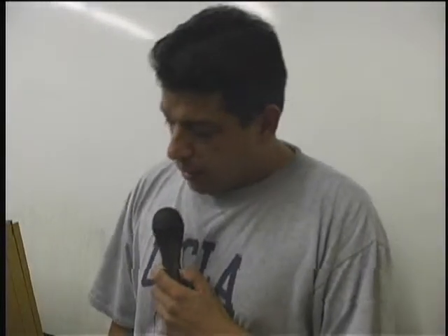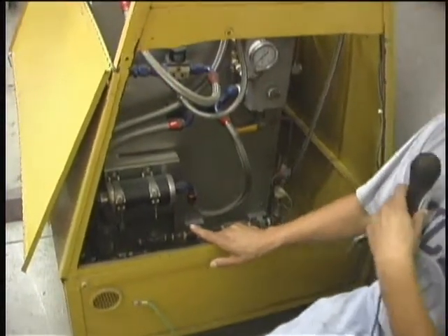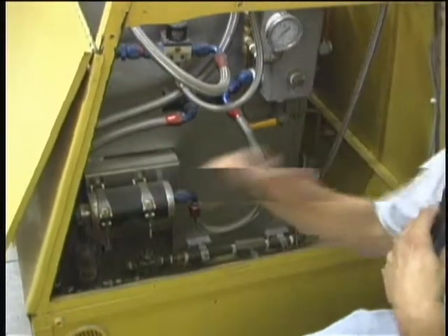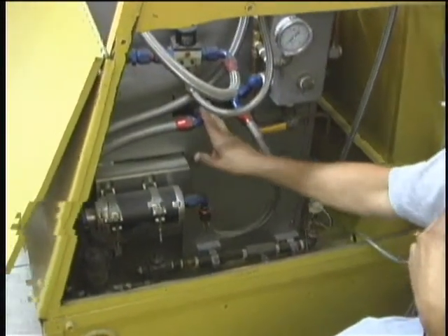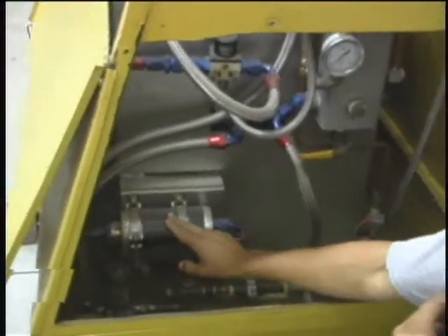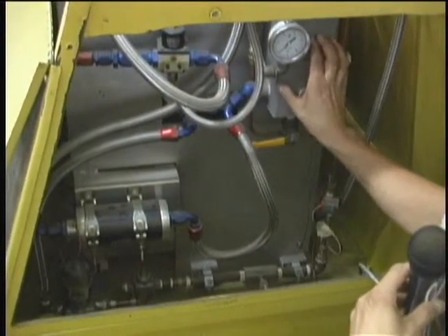My name is Miguel Lozano. Like Professor Ghoniem explained, this is the Northstar 2003 Northstar engine fuel tank, and here's a fuel system that we've developed for this engine. It's got a loop that goes from here to the engine and back. The output comes out of the gas tank to the high pressure pump, goes into the reservoir.